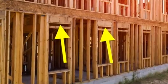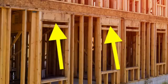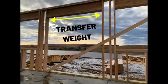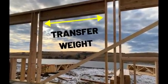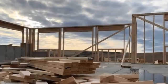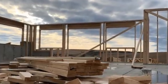For instance, you've probably seen these pieces of solid wood facing outward above an opening. These pieces are called headers, and they're very important. Doors and windows create hollow space in a wall, which means that studs aren't there to support weight from above. So the headers transfer the weight that would be in that space out to the edges of the opening. Really, they act the same way that a beam or girder does to carry weight over a span. They're like a bridge that creates a safe hollow space for the door or window to sit inside.